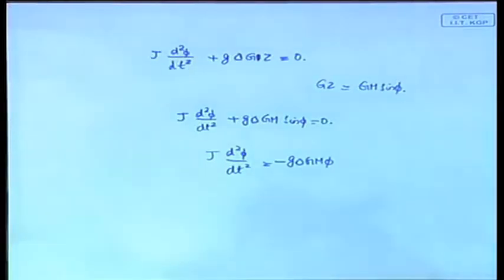This is the equation of simple harmonic motion, where you have your acceleration proportional to minus displacement. In this particular case, because of this condition the ship is going in a simple harmonic motion like this. Even though there is no heeling moment, it is still going in a simple harmonic motion because of its motion, it's causing it to heel like this.